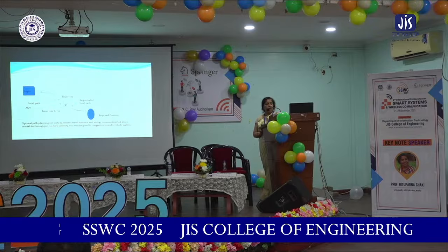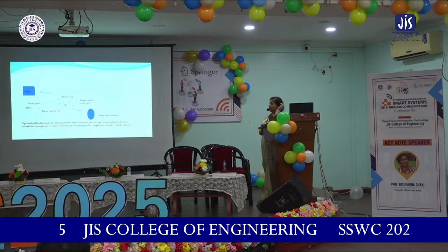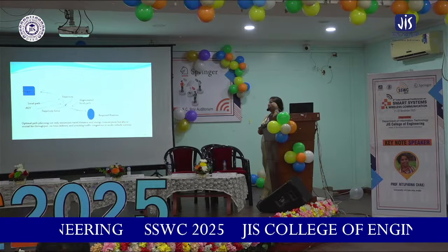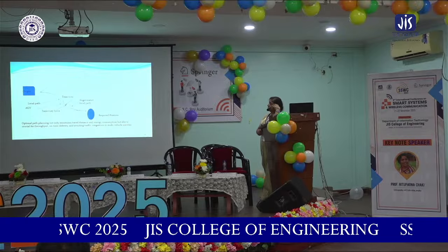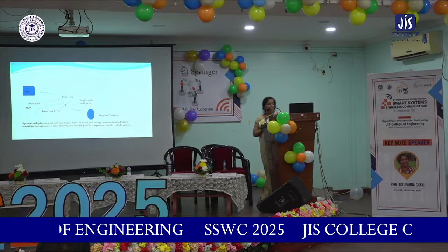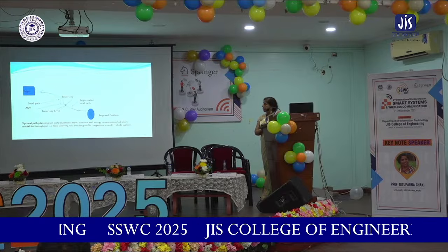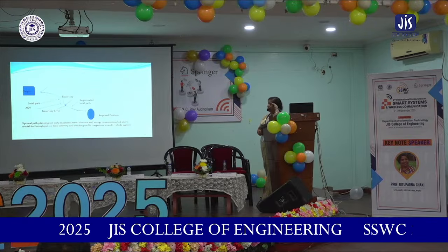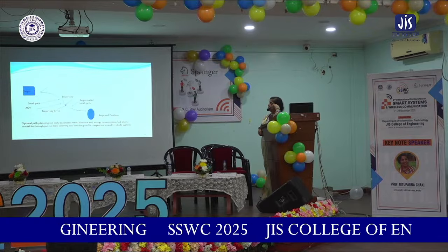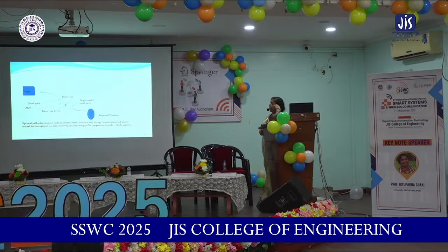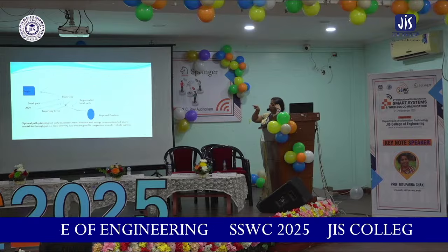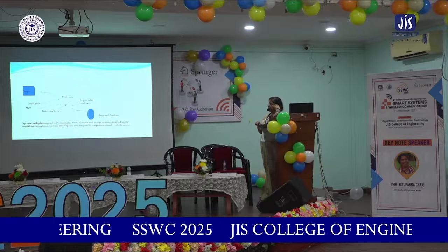So when you go for path planning, this is something which happens. You try to move from the origin to the required position by a robot. Whatever the trajectory is, in case there is a trajectory error, a local path is calculated, and a regenerated local path replaces the trajectory error.